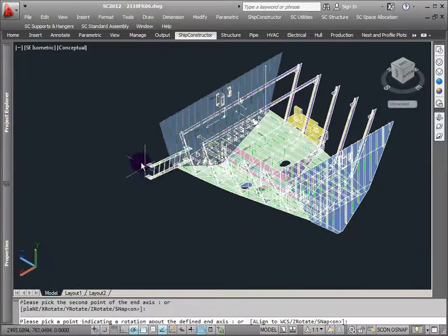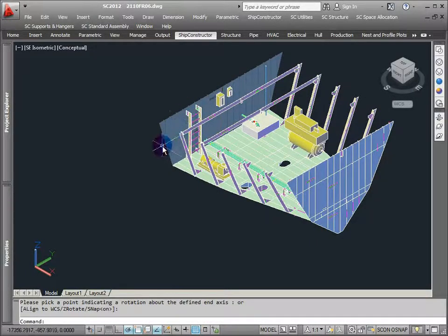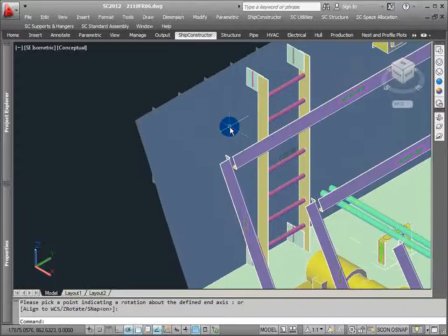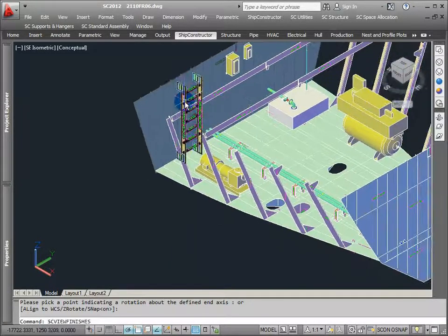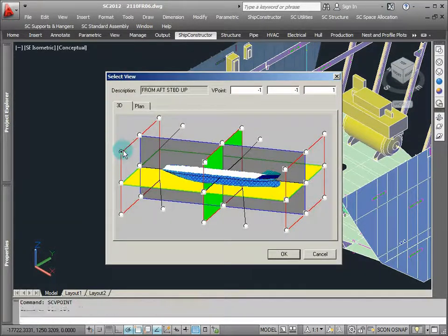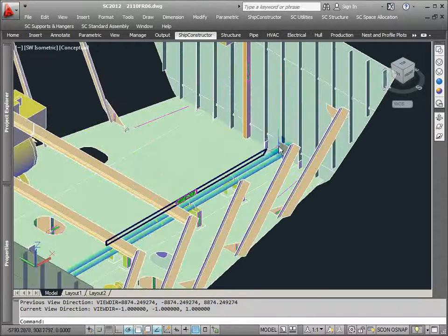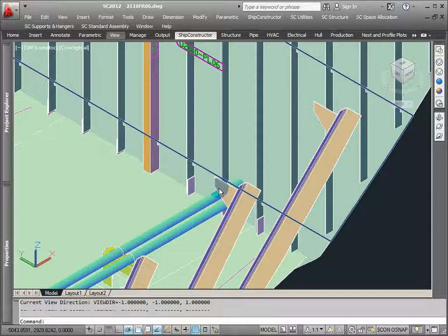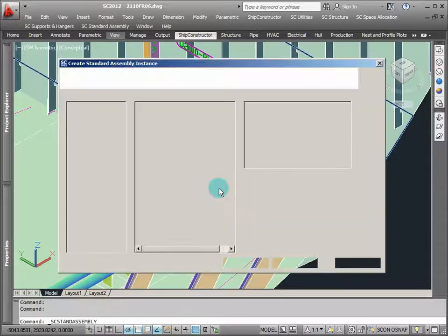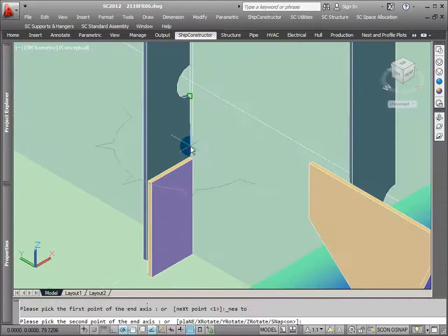It inserts the same way a piece of equipment does if you've done them, where you've got your planes that you can rotate it about during insertion. But the nice thing about this ladder is that it can have its own build strategy for that one object, right? Meaning that I can define a set of assembly drawings for manufacture of that one assembly, the ladder, with all the associated cut parts and construction sequencing events if it's a more complex object. Say, build it in this sequence, and then you have a final object. That one assembly drawing for that ladder can now be reused as many times as I want.